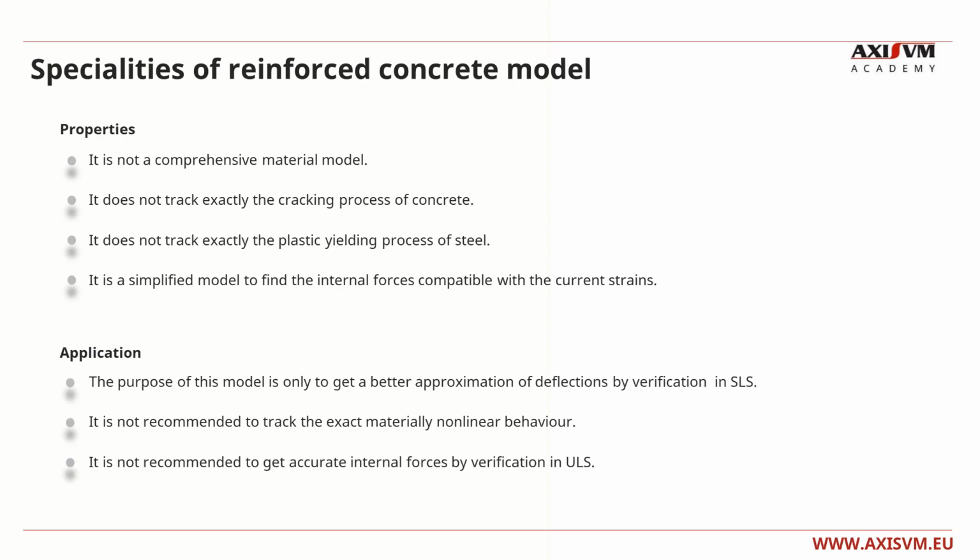The purpose of this model is only to get a better approximation of deflections by verification in serviceability limit states. Application of this model to track the material nonlinear behavior and to get accurate internal forces by verification in ultimate limit states is not recommended.